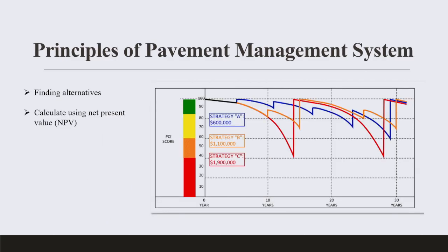So basically, how would we go? Again, I'm not sure about Nigeria here, but in the US, the vertical is the condition. So on bridges, we go 0 to 9. That's what AASHTO is telling us. 9 is the best, going down all the way until 0 is the worst. In roadways, we go 0 to 100. The PCI, or Pavement Condition Index, again, 100 is the best, 0 is the worst.